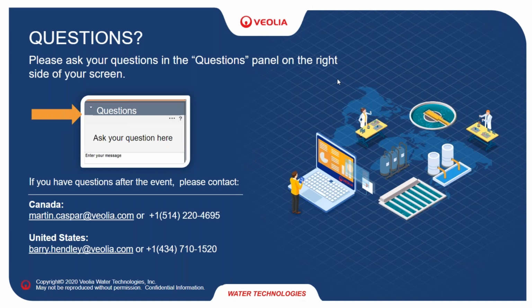With the soft version of Actiflo, yes, that's exactly what it's designed for, removing hardness out of the raw water and groundwater. So 300 parts of hardness, yeah, we could get. I want to say off the top of my head, I think we can definitely get that down to close to less than 50, probably less than 30 milligrams per liter hardness.